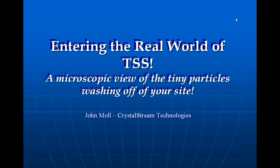Or bed load. And we have people today that take TSS to mean what's actually suspended. And the EPA test TSS actually pipettes out suspended particles. They won't be suspended long. They have to be agitated to get us. But anyway, total sediment load is really what we're looking at, because that's what's going to stop in your pond. That's what's going to stop in your sand filter. And that's what's going to stop in a manufactured device if it's sized properly.